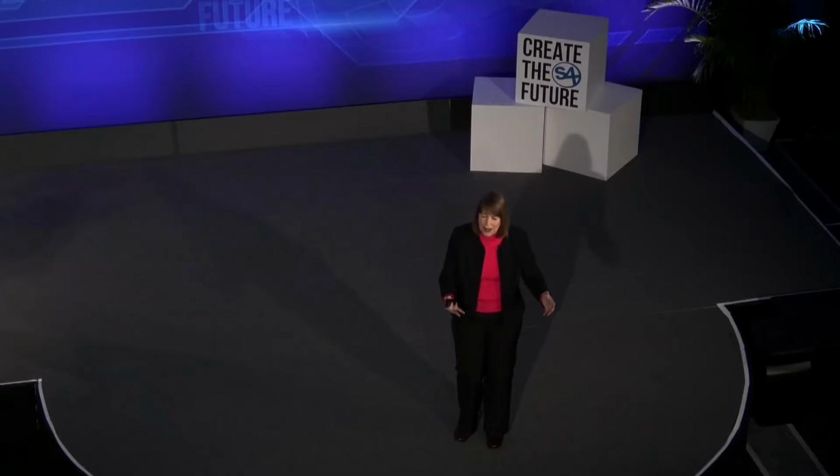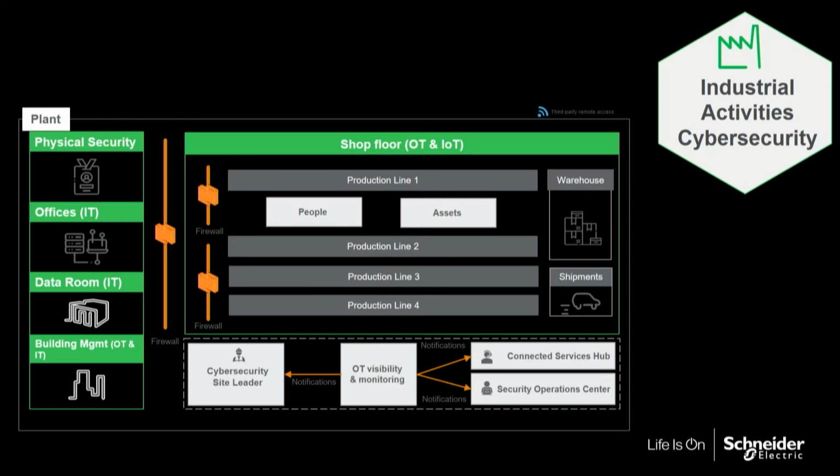And part of that also is that they are now responsible for any new product lines that they must be following the IEC 62443 standards. So again, ask your suppliers. It's an odd question. I still haven't received a request on that. Is this product being created on an IEC 62443 line, right? It's new, it's rare that people are going to that level yet, but that's where we need to go as an industry.